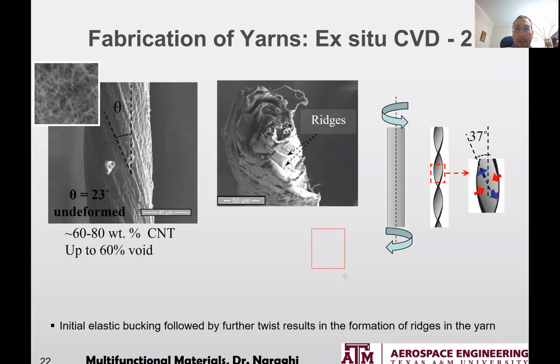If I apply a shear force like that, which is what the twist does, and I look at another plane in this guy, which is 45-degree rotated, and I calculate the principal stresses, I will have these principal stresses. I will have tensile and compressive, normal, and basically these are with respect to this normal direction.